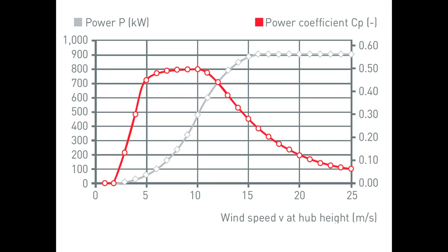So you are going to apply some pitching angle, and accordingly your CP is going to change, but up to the rated wind speed we are going to extract as much maximum power as possible. We are keeping beta 0. So up to this point your CP is a function of lambda and beta, but in this case beta is 0. So CP varies with the change in wind speed because lambda is going to vary, and afterwards it is a function of lambda and beta.